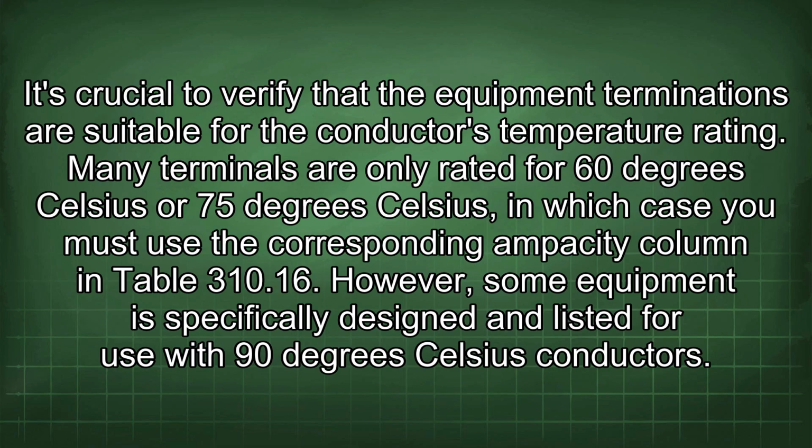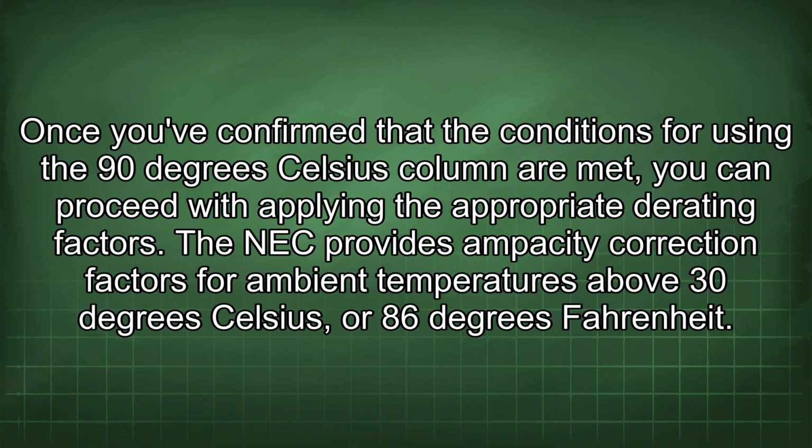It's crucial to verify that the equipment terminations are suitable for the conductor's temperature rating. Many terminals are only rated for 60 degrees Celsius or 75 degrees Celsius, in which case you must use the corresponding ampacity column in Table 310.16. However, some equipment is specifically designed and listed for use with 90 degrees Celsius conductors. Once you've confirmed that the conditions for using the 90 degrees Celsius column are met, you can proceed with applying